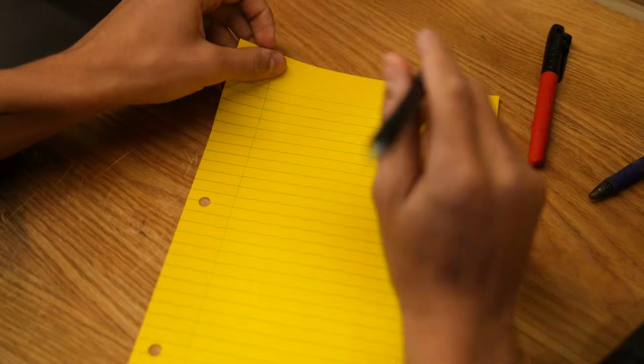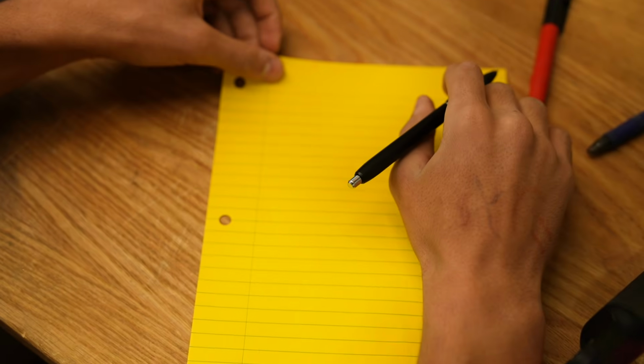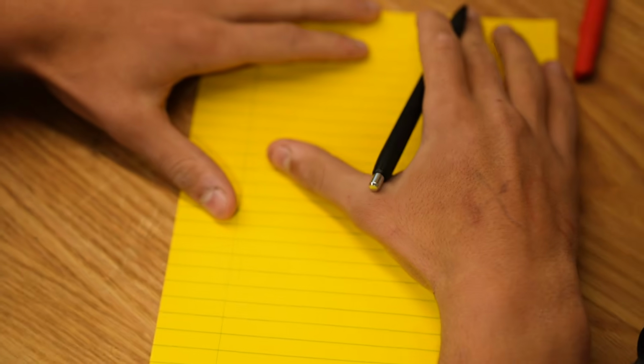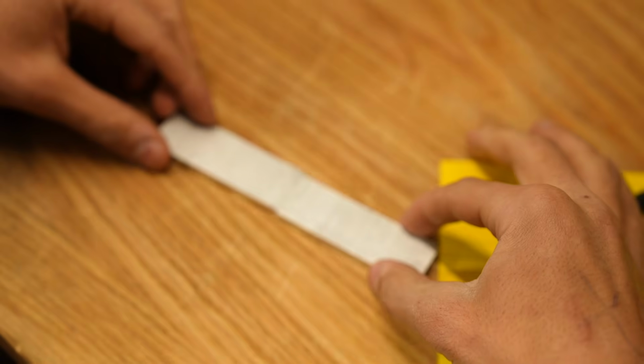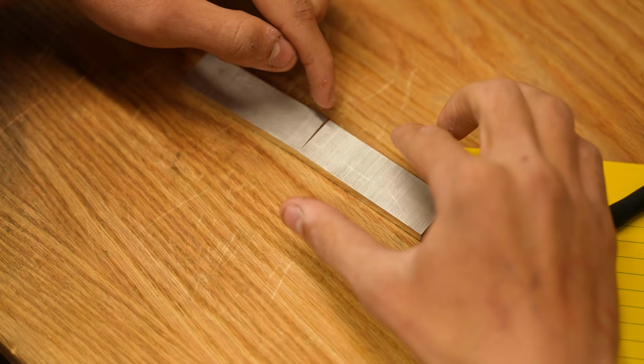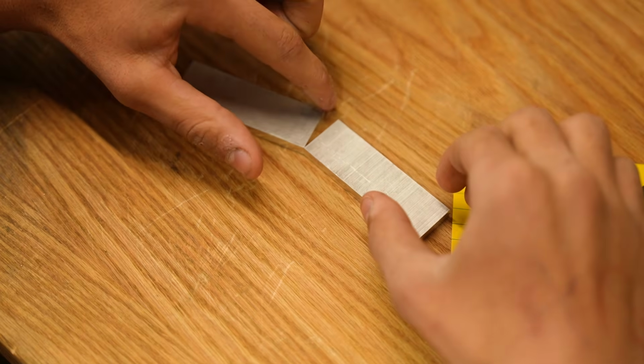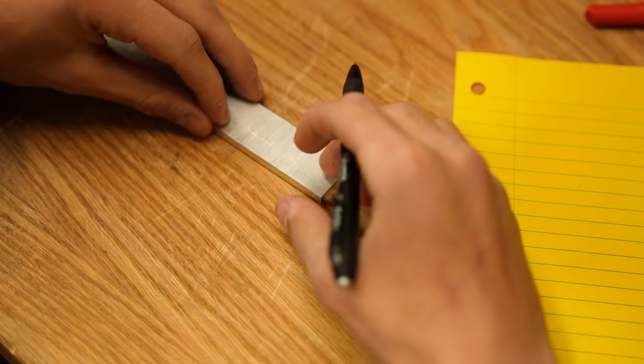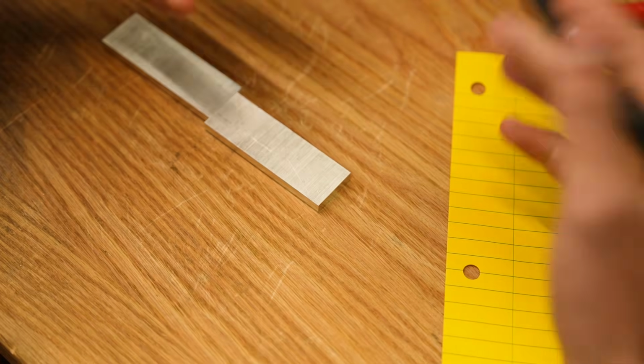All right. So first, we need to go over some terms. The process of structural analysis by hand is really comprised of finding what are called points of interest. If we have, for example, this beam that we're analyzing, and we want to see when it will break, if you bend it, you might intuitively know that it will crack on the top here. So what we would analyze is that point for the stresses there. These equations that we're going to walk through are how you find the stresses at these points of interest, although you can find the stresses at any point. If we wanted to know the stress at this point here, we could, but it wouldn't be our point of failure.